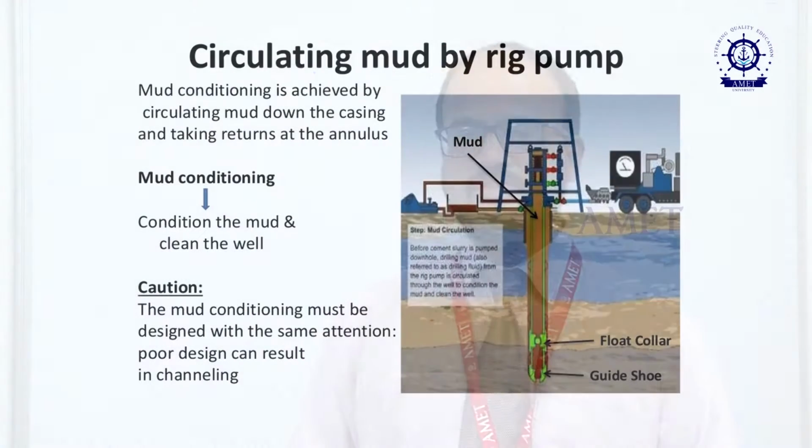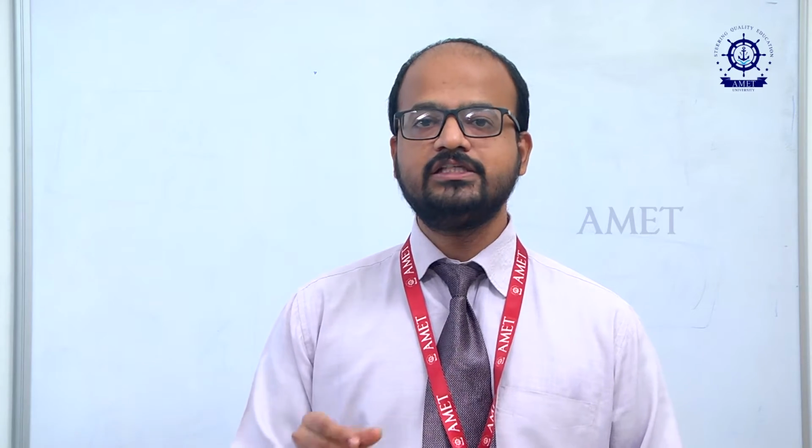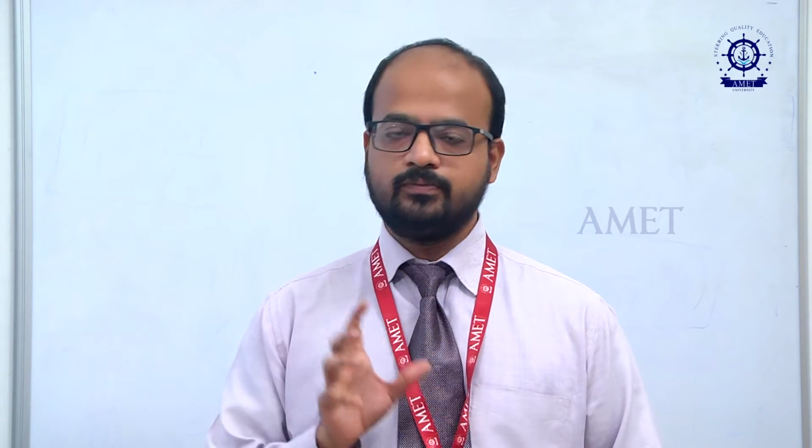Now the second step is we have to fill our well completely with mud. That is called mud conditioning. Once in the drilling progress, we are using drilling fluid. That drilling fluid forms a mud cake inside the wall of your well bore.